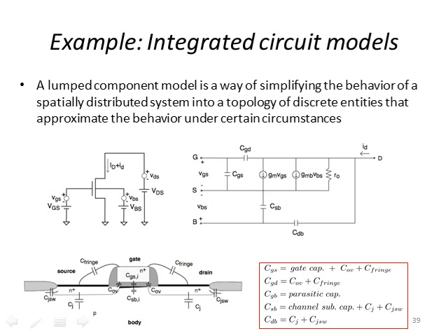So you'll apply a gate voltage, and you're going to induce some AC current through this I D, and then see how this AC behavior in frequency is affected by all the different capacitances. In the semiconductor course, or in the circuit analysis course on semiconductor devices, you will see these AC models. The origin is really a two-port network model.